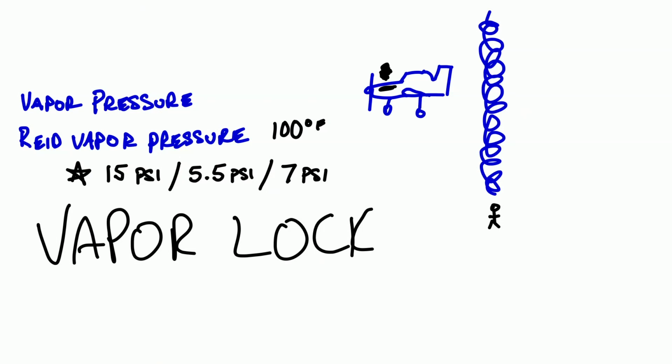Now, this is all kind of important because obviously, as an aircraft flies through different ranges of altitudes, it's going to need different things that allow it to function. This whole issue with vapor pressure that we're talking about here is one of the reasons why we use things like boost pumps in an aircraft fuel system to help avoid any issues with vapor lock. If we did start to form vapor in the lines, the pumps rather will create a positive flow of fuel all the way through the fuel lines, all the way to the fuel metering device that happens to be putting fuel into the engine.